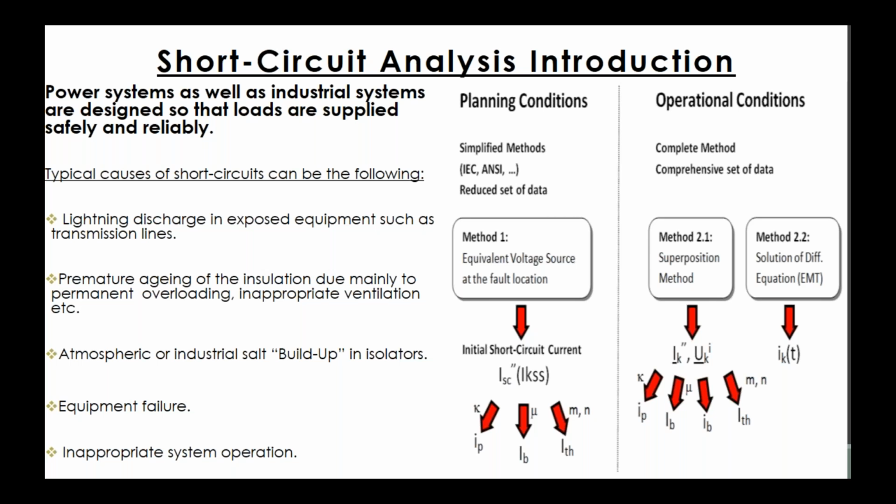The short circuit calculation in PowerFactory is able to simulate single faults as well as multiple faults of almost unlimited complexity. Although systems are designed to stay as free from short circuits as possible, they can still occur. Short circuit conditions generally cause large uncontrollable current flows, which, if not properly directed and handled, can result in equipment damage, the interruption of large areas instead of only faulted sections, as well as placing personnel at risk. A well-designed system should therefore isolate the short circuit safely with minimal equipment damage and system interruptions.